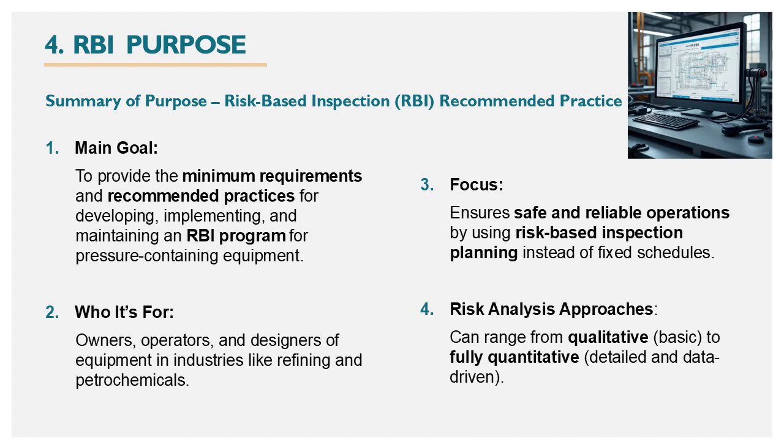Agenda number 4 is risk-based inspection or RBI purpose. The purpose of RBI is to optimize inspection resources by focusing on equipment that poses the highest risk. This helps reduce unplanned failures and improve asset integrity. Summary of purpose, risk-based inspection or RBI recommended practice.